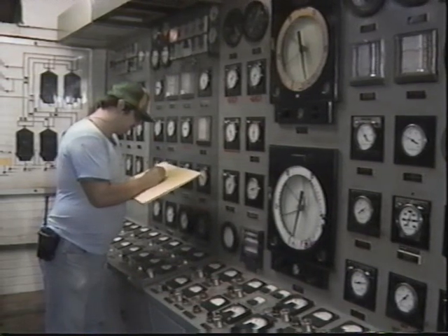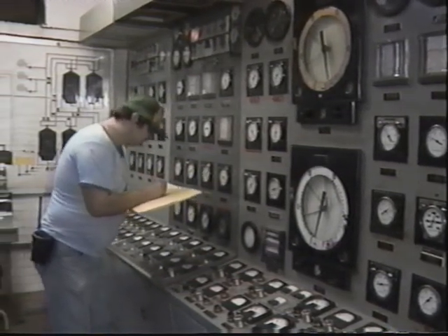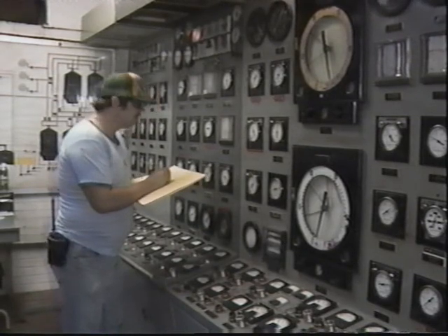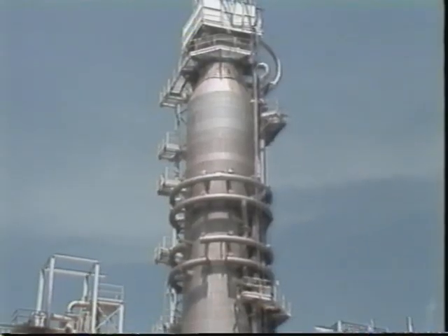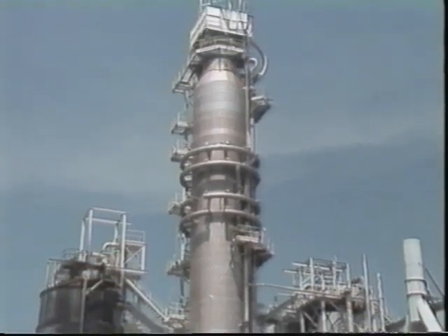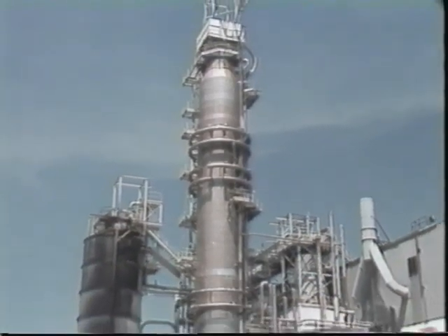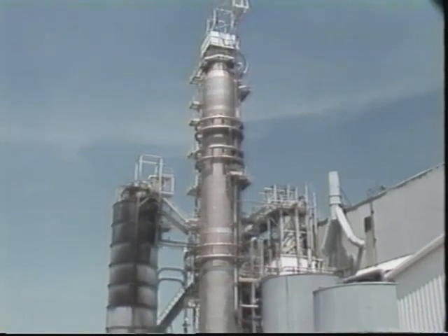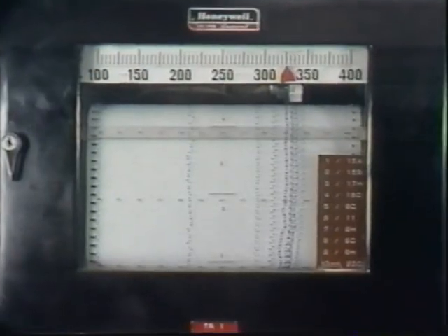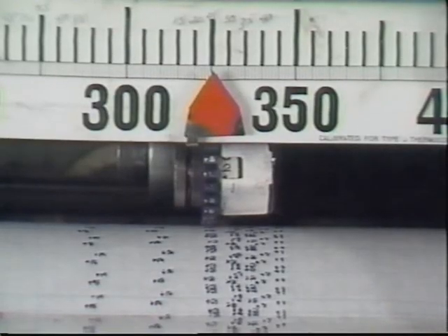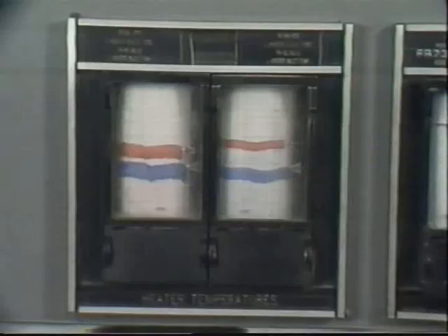As we said earlier, poor steam circulation in the digester could also lead to a high debris level, and it could do so without necessarily affecting the K-number. One way to check the circulation is by referring to the process variables relating to the steam flow in the digester. Sometimes there's a trapped air pocket in the digester that impedes steam flow circulation. The air pocket can also create false pressure readings in the digester. The pressure and temperature readings are checked, and a discrepancy between the two is detected. The discrepancy could be caused by an air pocket.